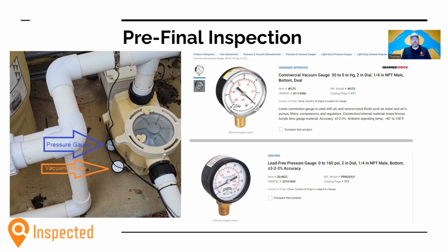We take these two numbers that the pump is reading at its maximum capacity in both pool and spa mode where applicable. We put them into a formula and it shows us what the total dynamic head, or resistance to flow, is in your pool. We then take that information and put it on the pump curve, and that will show us the gallons per minute the pump is operating at maximum capacity. From there, we'll compare that to our previous inspection, and it should show that you have sufficient pipes to flow the pool in less than 8 feet per second.